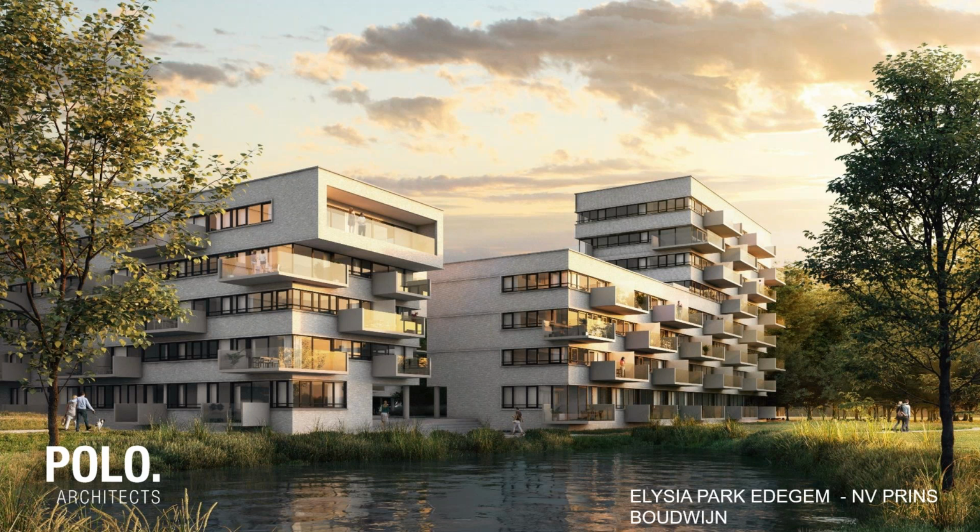Yeah. Well, that's fine. I think the whole product, BIM 360 Design, there's so much to it, yet very easy, but people have to start somewhere, right? And I think if you're used to working with central files, save to central, reload latest, that's the first step, and that's what I would advise. It's what you're used to, that's what you can bring forward into BIM 360 Design as well.